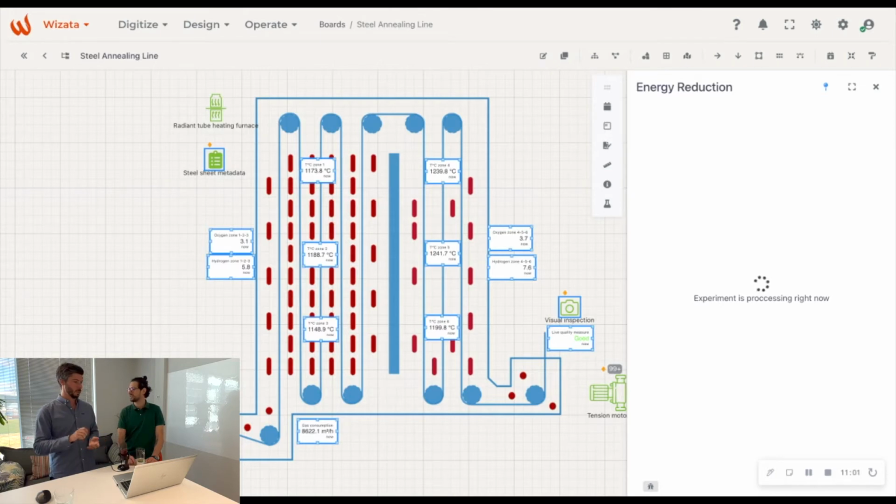A set point is something that you can tune and adapt or change. You can control. Okay. While the rest is just information that is tracked, but you cannot directly impact. Okay, I get it. The temperature is actually kind of in the middle, because temperature is the consequence of a gas set point. But in most cases, what we will have is some PID systems in the back where you set your temperature, and the PLC calculates the amount of gas to send to reach the temperature. So in some cases, temperature can be considered as a set point.